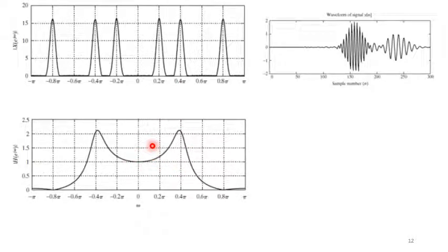If we look carefully, you can see that at the frequency around 0.4 pi, the magnitude response is around 2. So that means those frequency components that are around 0.4, whether plus or minus, I think that's visible to you, they will get an amplification of around 2.